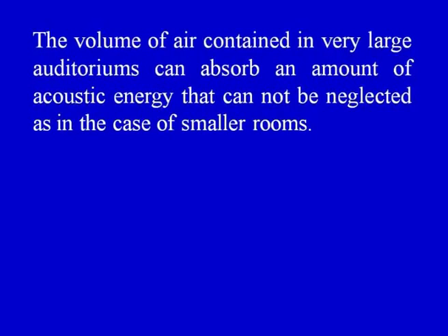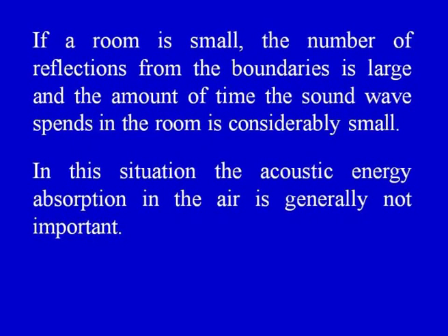Now, let us consider the effect on reverberation time of the humidity in air and sound absorption in air. The effect of absorption of sound and humidity in air on the reverberation time needs to be considered. Sometimes, you see, the volume of air contained in very large auditoriums can absorb an amount of acoustic energy that cannot be neglected, as in the case of smaller rooms. If a room is small, the number of reflections from the boundaries is large and the amount of time the sound wave spends in the room is considerably small. In this situation, the acoustic energy absorption in the air is generally not important.